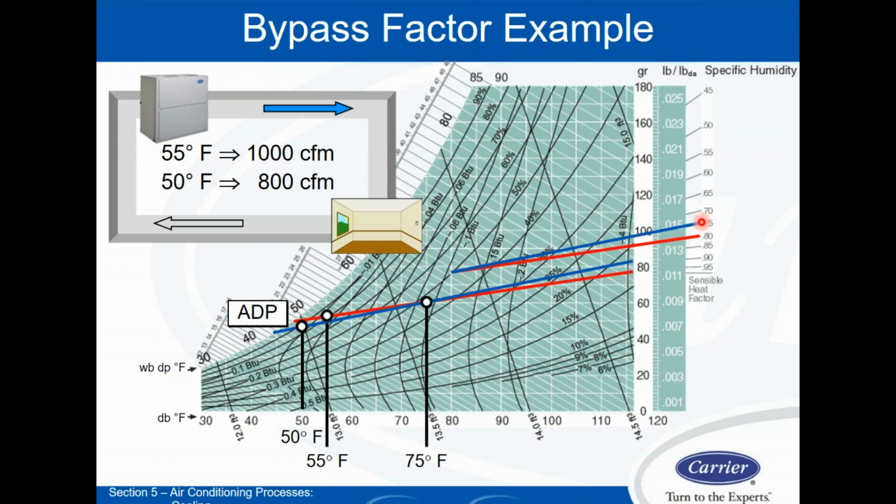So the blue line is a 0.75 sensible heat ratio. And I'm putting my ruler on there to line it up with one of these lines over here to get that ratio, and then I'm just sliding the ruler down to see my process. So in this case, here's my process line in blue. If I had a 0.8 sensible heat ratio, which means I'm doing 80% sensible, 20% latent, I'm not doing a good job dehumidifying, I would have this red slope, and then my actual process line would match that slope. So I slide my ruler down, that's this red line here, and you can see I'm going to have a resultant higher conditions off of the coil over here.